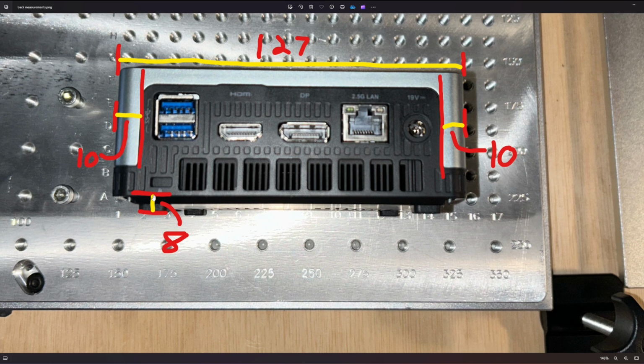We have 8 millimeters from the bottom, from the base of the little nubs here for the spacers, up to where we want to make sure we're clear so that the heat can actually escape and not get trapped. And we have measurements from each edge, and we have a total width. So our total width is 127 millimeters, and we actually used 130. So we have a little bit of breathing room just to make sure we don't have a problem getting it in and out. And we want to go 10 millimeters in from each edge, and that way it doesn't slip out the back or anything like that.